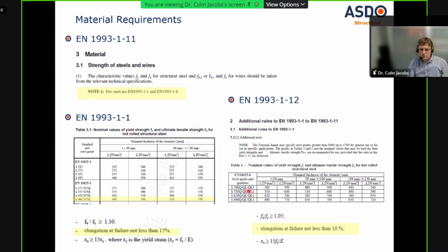If we look at design resistance calculation, IS 800 gives us the tension member calculation. Again, very simple calculation. Again, you'd all be well aware of this. But one thing to note as a difference from the Eurocodes is that when you're calculating the area of a thread, they use the root area of the thread and not the stress area as the Eurocodes do. That can make quite a bit of difference to your calculation, so you should be aware of that.